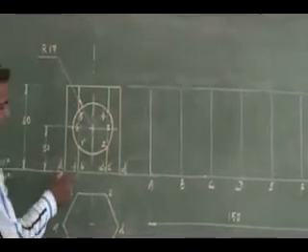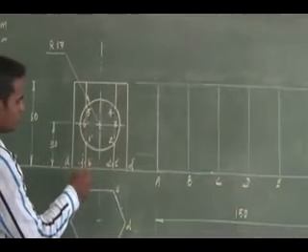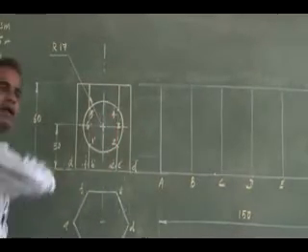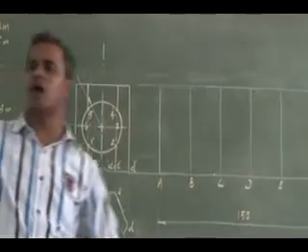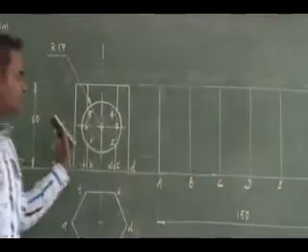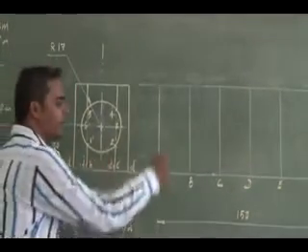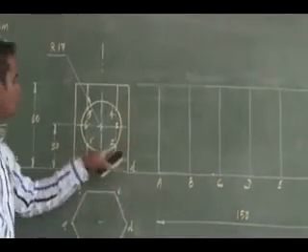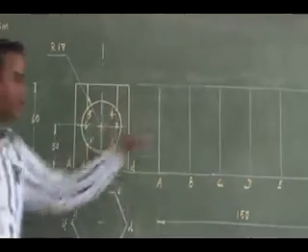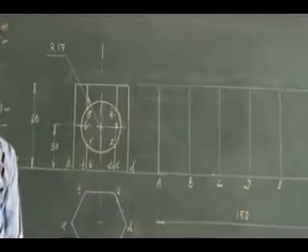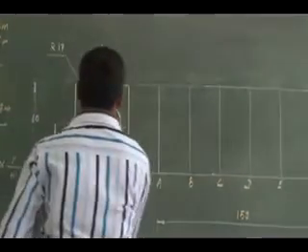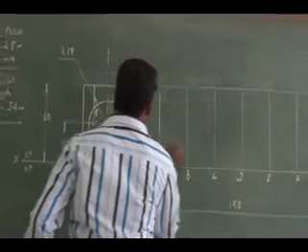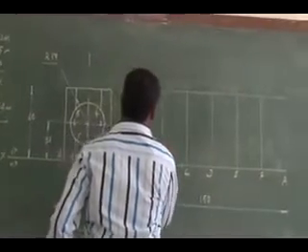You see, look at AB. First of all you mark these 1, 2, 4, 5. It is clear I can mark them by drawing a horizontal line, extending the horizontal line and marking it on the corresponding vertical edges. So 1, 2, 4 and 5, you mark on the corresponding vertical edges directly by extending the projector. So from 1 and 2, I can draw projectors.